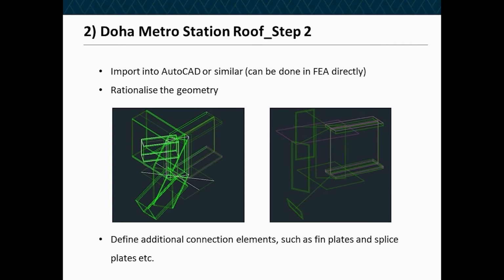So if we wanted to sever the joint between this box here, that you can just about see coming out in this direction, and this one over here, we might want a plate that ran through the middle so that we could make that connection in real life. Okay? And if we wanted to do that, we would insert that plate just as a rectangle into AutoCAD using the functionality of the local coordinate system.